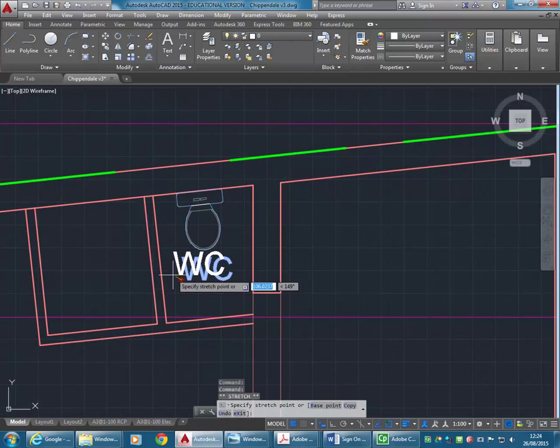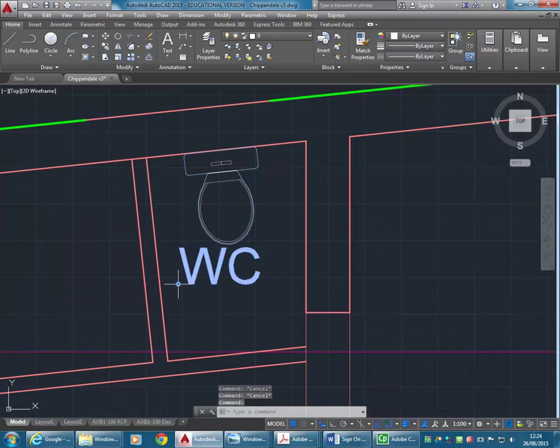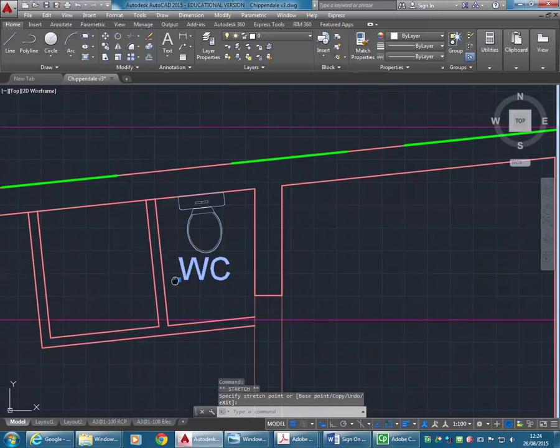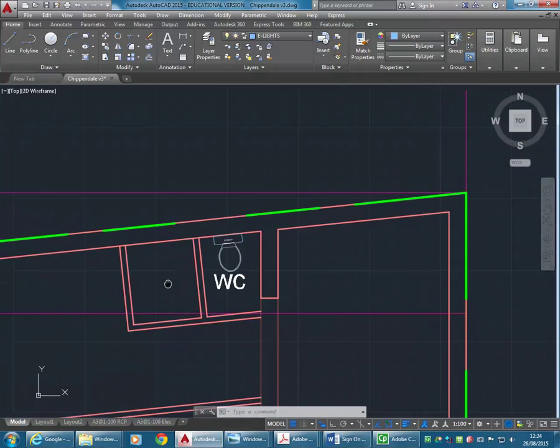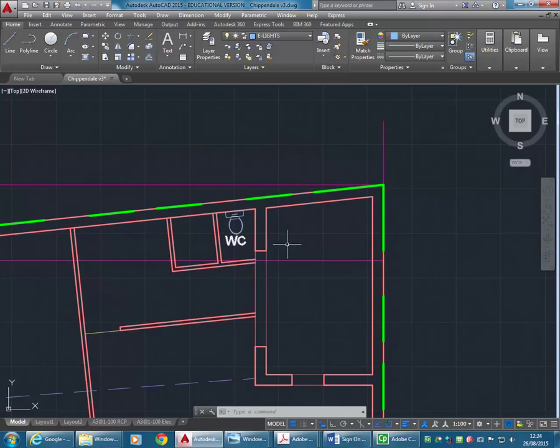And it's up to you how you place that, but it's important to label. Sometimes people just get so used to having those symbols read on the plan that they don't label everything. And it is really important with construction drawings to label every fitting so that it's itemised in the schedules and other things. The people pricing it need to do all of that and be able to clearly notate everything that's indicated. So on your proposal, you'll definitely need to make that clear as well.